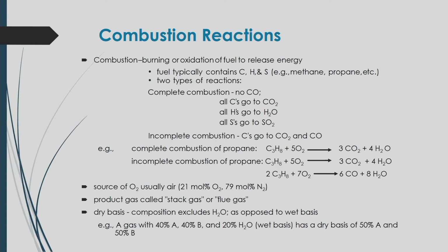So, this problem is a very good example of how to do the material balance with chemical reactions, with single-pass reactions, and with multiple units. Also you can check whether there is any bypass or not, any recycle or not, any purge or not, or any makeup or not. Based on all those components you can practice this problem, and you can get the idea of how to do the material balance. Next we will consider the material balance based on combustion reaction.